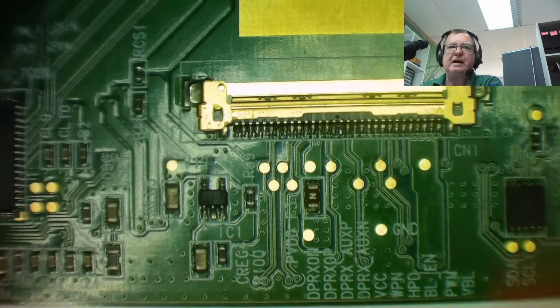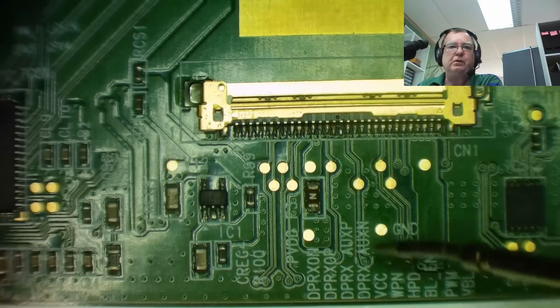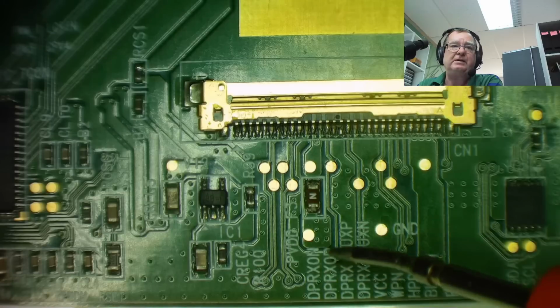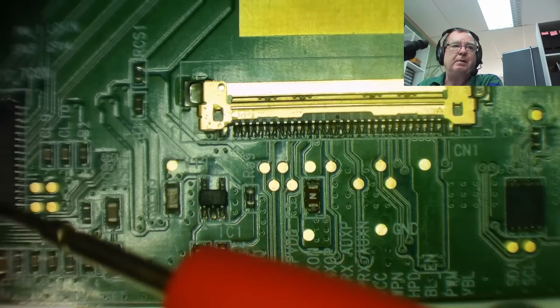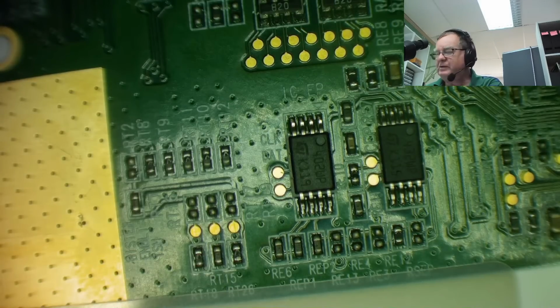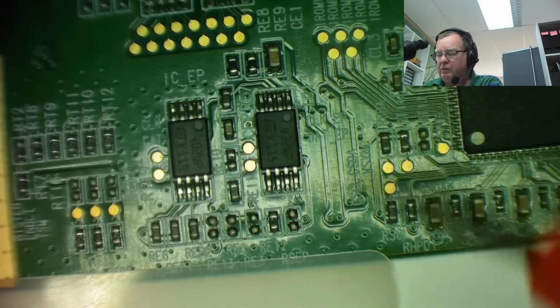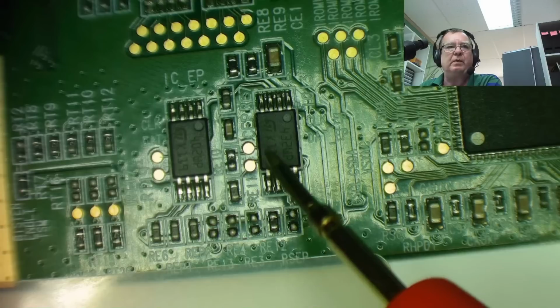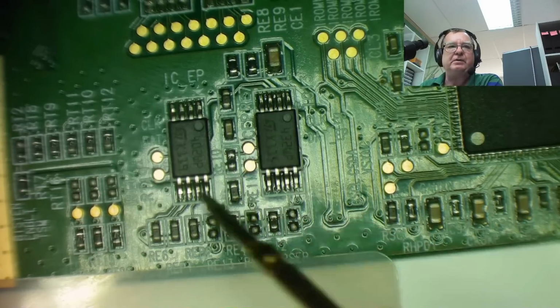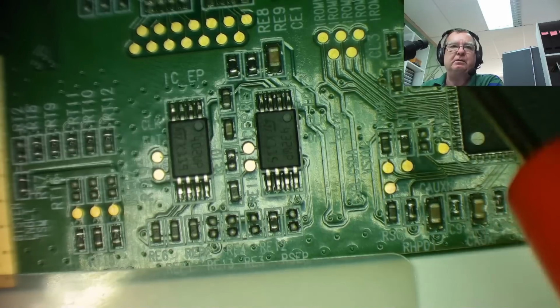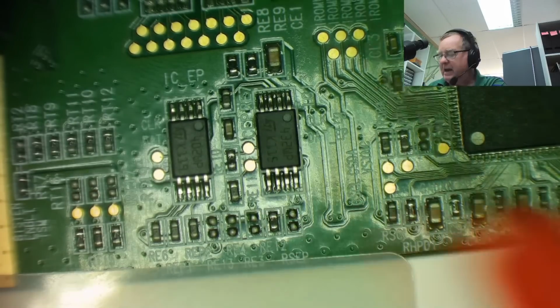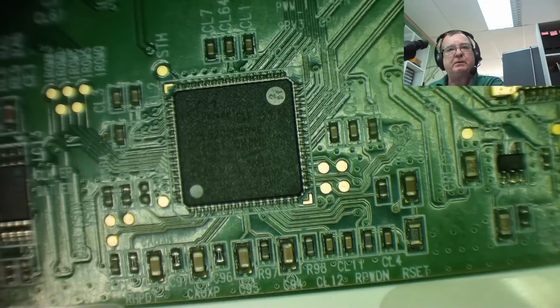So we know the computer detects both screens. So I think we can assume that the AUX channel, AUX lane, is working fine. So there's either a problem on this lane, the video lane, or there's a problem with the chip. The two EEPROMs I was interested in effectively hold what's called EDID, Extended Display Information data, which basically holds the data about this screen, the resolution, how many colours, the make, the model. So it would again suggest that they're okay, because the information is going back to the computer on that AUX channel.